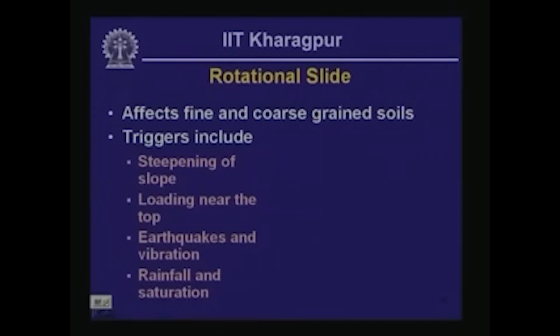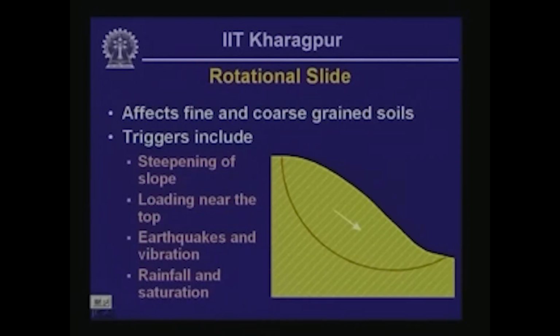of rotational landslides. So this is a rotational landslide in which we are looking at a cross section of a slope underlain by relatively homogeneous soil or rock. In many cases, the slope failure is going to have a circular failure surface, as indicated by the orange line there, and the mass of soil or rock above that circle is going to start tumbling downslope.